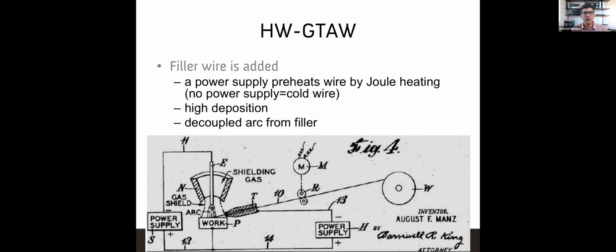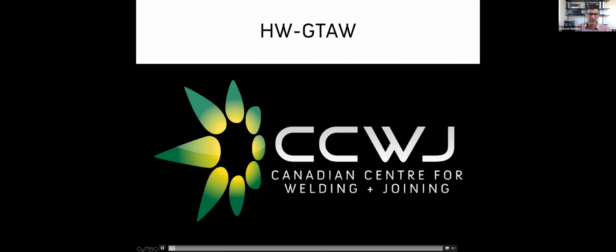When do we want cold welds? For example, in stainless steels, we don't want the weld to get too hot or to take too long to cool down, because the stainless steel can sensitize. Hot wire is a really good technique for that. Let me show you a video of a hot wire done in our lab.